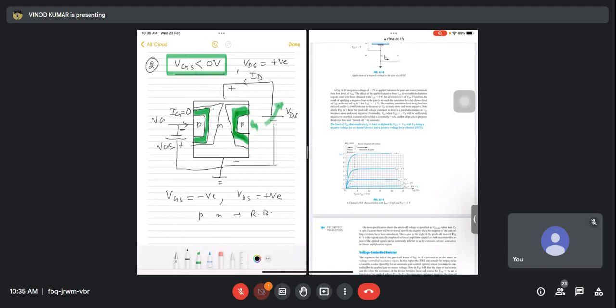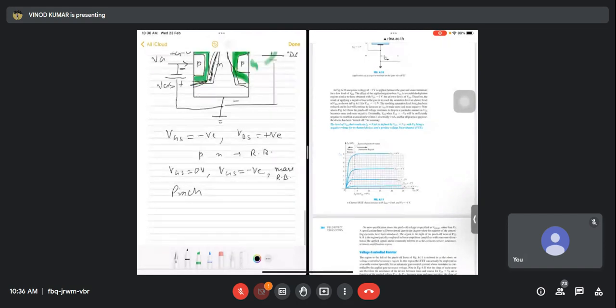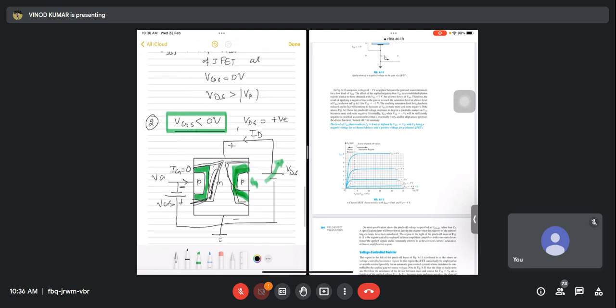Okay, तो saturation क्या होगा, जल्दी आएगा because depletion width जल्दी बनेगा as compared to VGS 0. VGS negative जो है make this PN junction more reverse bias. So the pinch off we are getting is earlier than VGS is equal to 0. Pinch off means this situation.